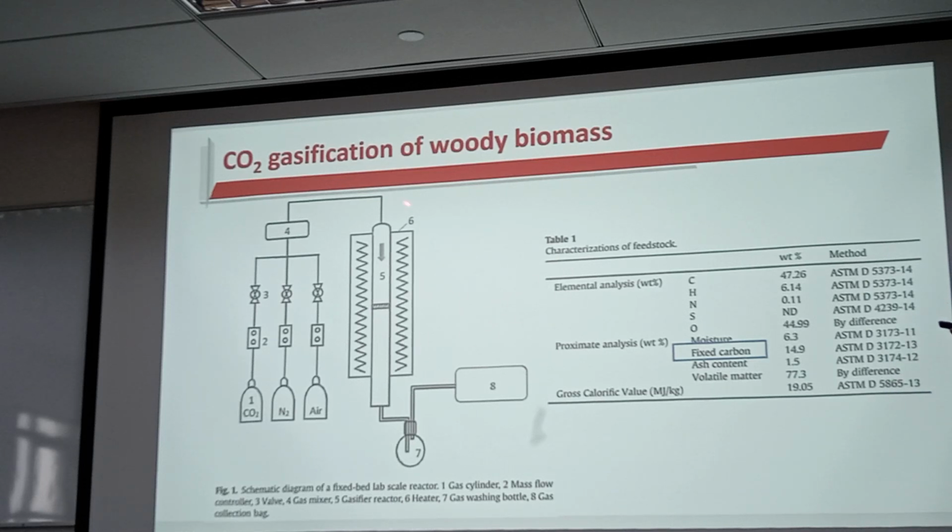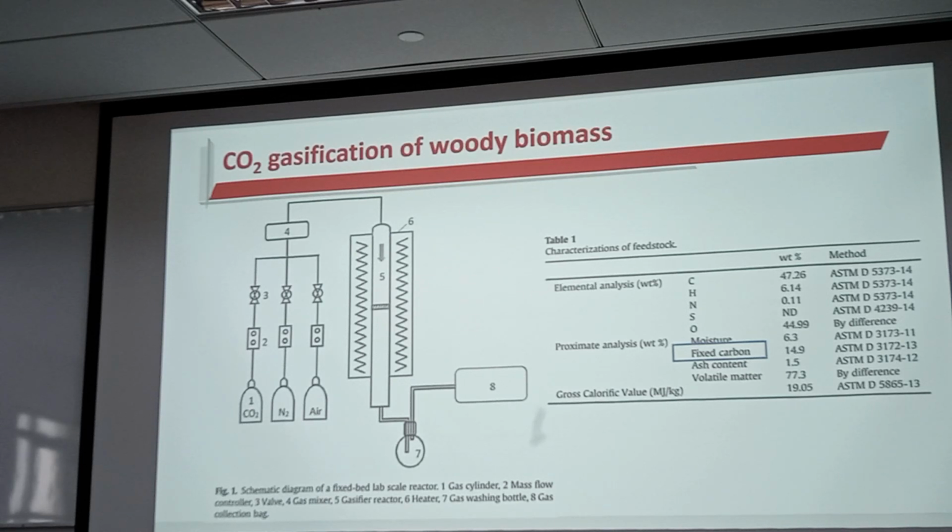After that, it will go through the fixed bed area. So we will heat the system over here. On the wall, there are 2 heaters to maintain the temperature in the gasification process. Usually for the gasification process, the temperature should be controlled in the range of 700 to 1000 degrees centigrade. At the end, you can collect the samples for analysis.